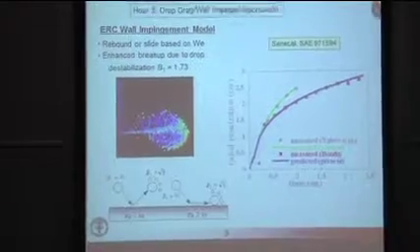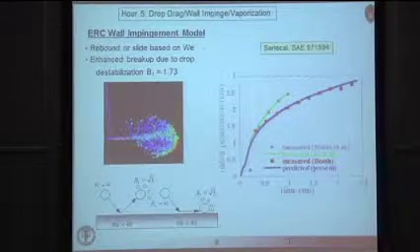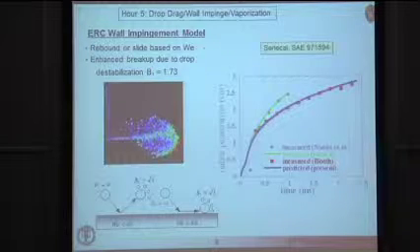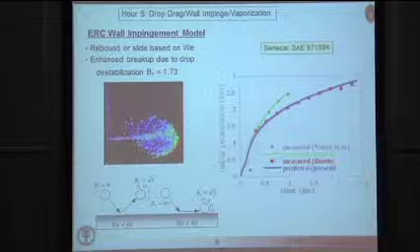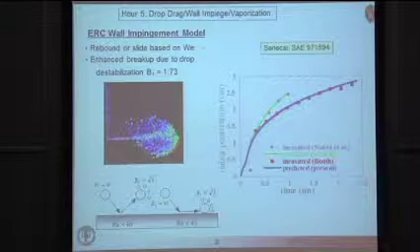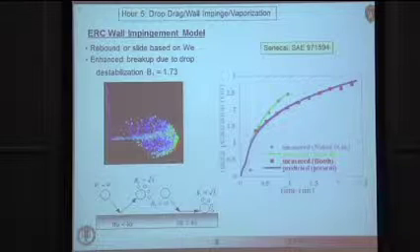Okay, so the other thing that happens when a spray impinges on a surface is that the droplets become destabilized, if you like. Remember I mentioned that there were some constants in the breakup models that essentially associate a breakup time with some initial condition, some initial disturbance.